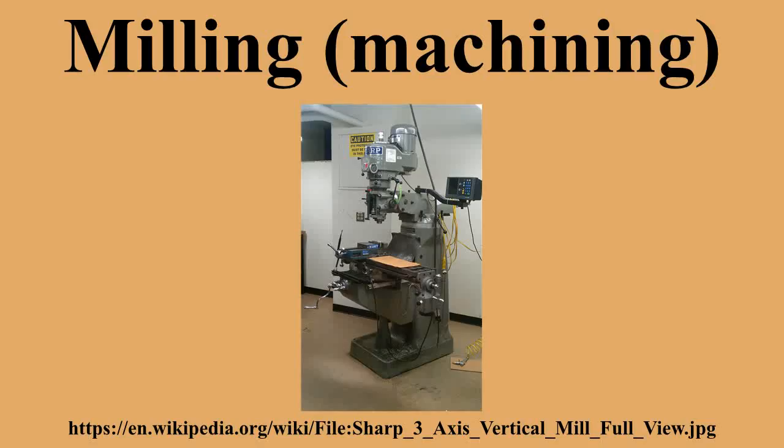While end mills and the other types of tools available to a vertical mill may be used in a horizontal mill, the real advantage lies in arbor-mounted cutters, called side and face mills, which have a cross-section rather like a circular saw, but are generally wider and smaller in diameter, because the cutters have good support from the arbor and have a larger cross-sectional area than an end mill. Quite heavy cuts can be taken, enabling rapid material removal rates.